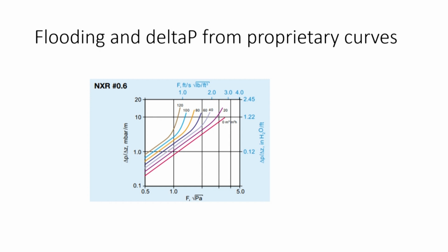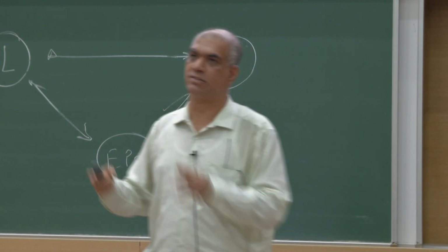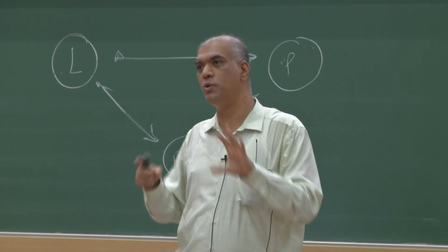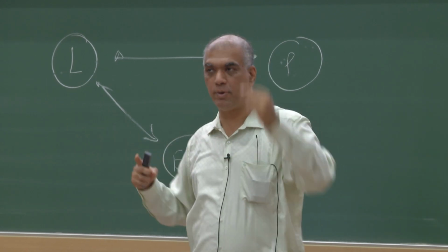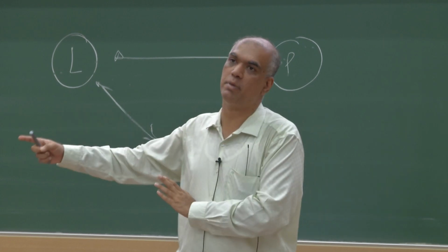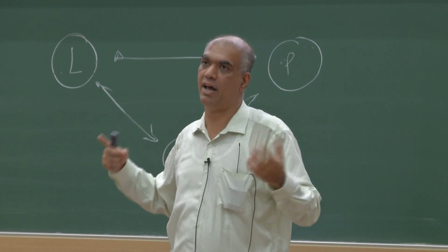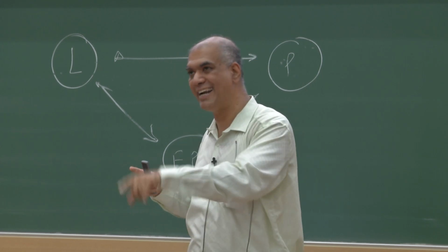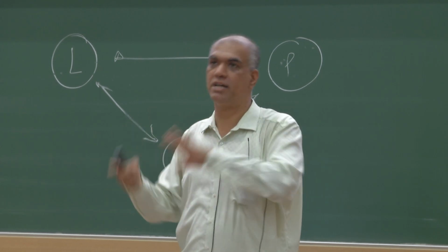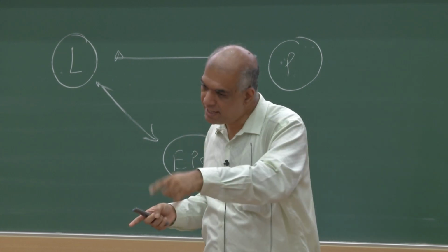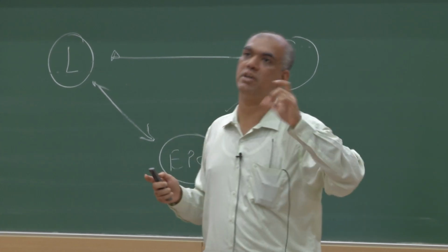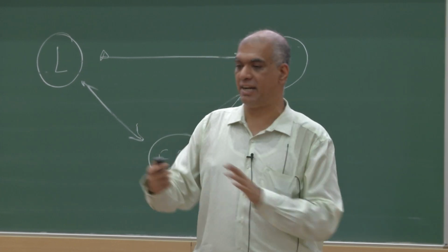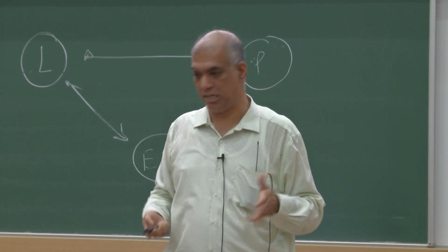But a lot of times, if you go to the vendors, whoever is selling you packing, Sulzer, etc., they will have a lot of data sheets. What I'm motivating you is to switch between equation-oriented design and design based on data sheets. A lot of people love, and it's a realistic design, if once you have found out the numbers, you go to a data sheet, put in the right parameters, and actually convince yourself that the HETP is whatever or the delta P is whatever you have assumed, right? So equations are just one way to design. Often real design will be based on data sheets.